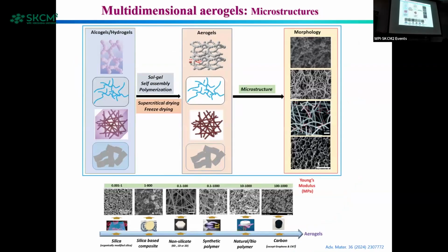There are different multidimensional aerogels. As I already told, one can synthesize aerogel in any form. One can synthesize particulate or colloidal based aerogels, mostly silica based or metal oxide based aerogel. This is the pearl necklace morphology, where you get connections of particles. Okay. One can synthesize polymer aerogels also, with a fibril-like network, mostly polyamide aerogels; with polyurethane, you can get a fibril-like polymerized network. And nanofibers or nanoparticles you can disperse and use the freeze drying concept, and one can synthesize fiber type aerogels. A knotted structure you can observe, with connections between the fibers, using this type of synthesis.